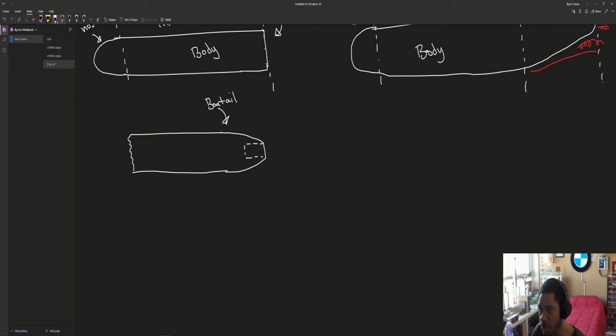And what happens is that your nozzle is exhausting, and you want your flow to try and come down into it nicely. Like this. So instead of having it just cut off, with that base drag, you have this so that it has a more laminar flow type.